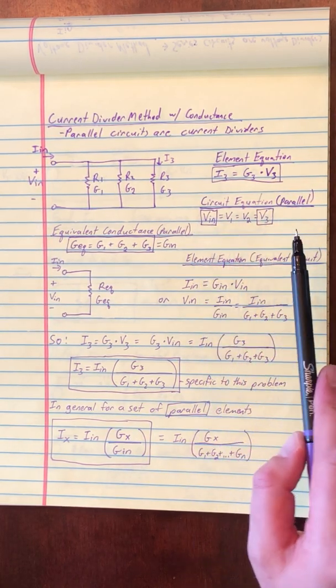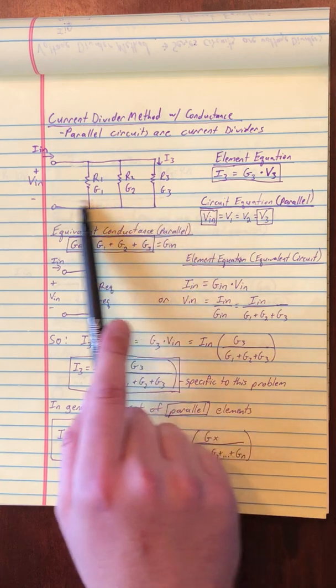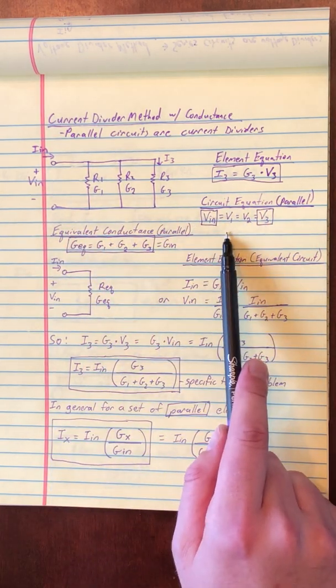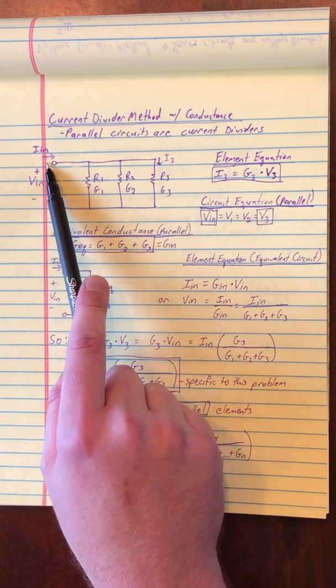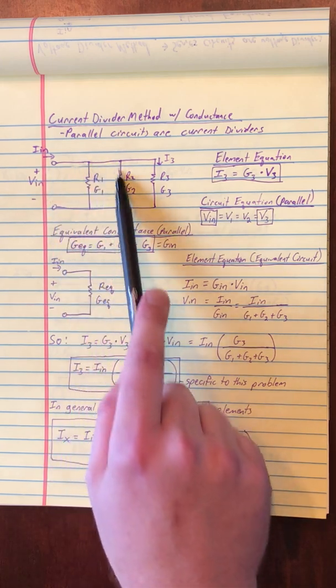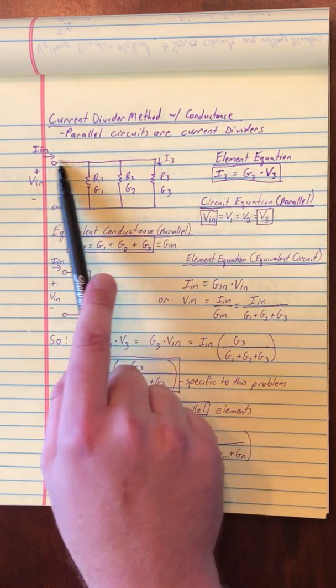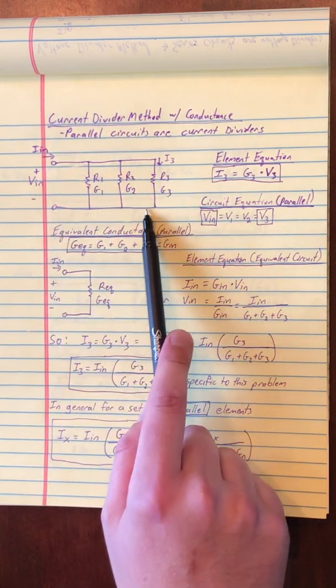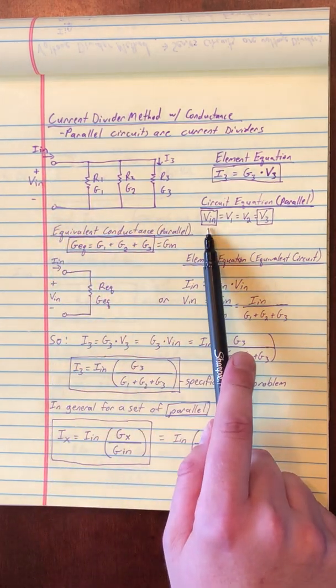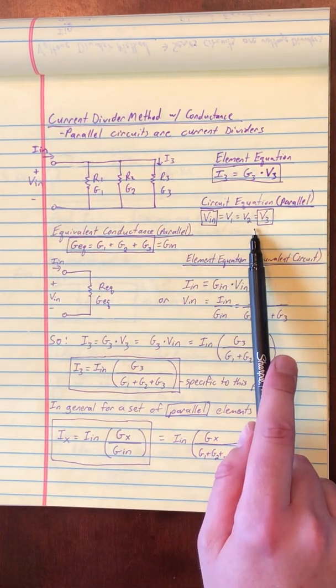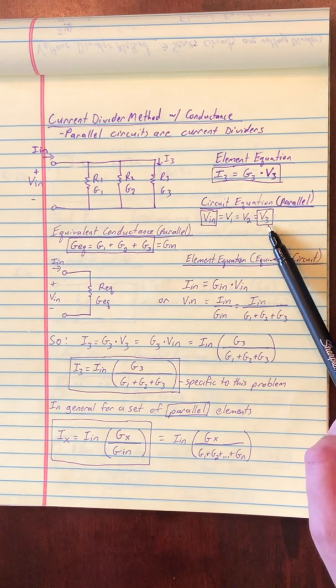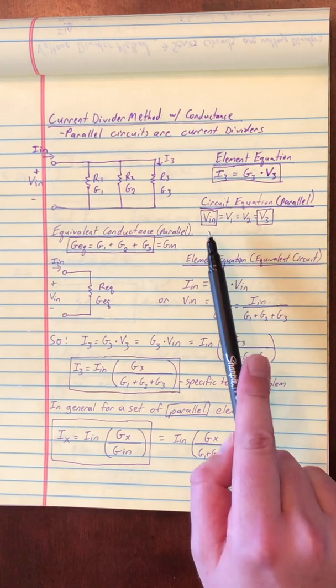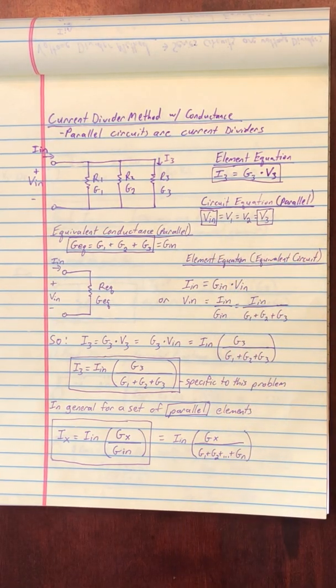The circuit equation, we already used the current law, so this is the voltage law. So any voltage gain around a loop is equal to the voltage drop, and we can see that each of these includes a singular loop with a singular resistor and the input voltage. So Vn is equal to V1, equal to V2, and equal to V3. Since we're interested in element 3, I've boxed that V3 and Vn are equal to each other.